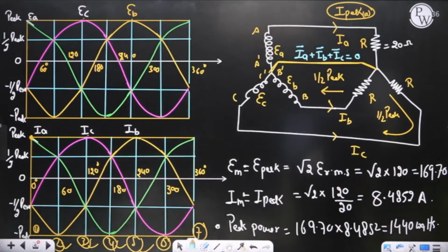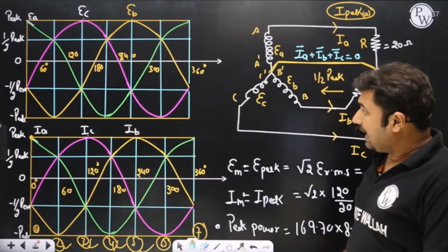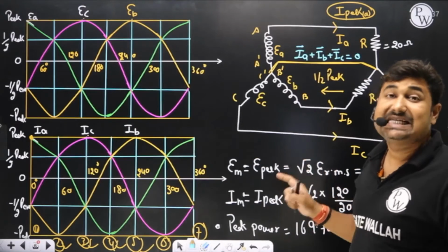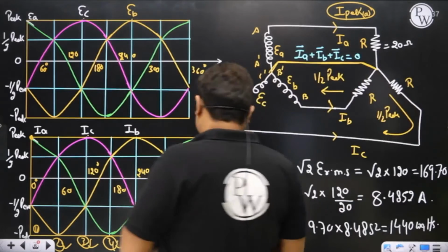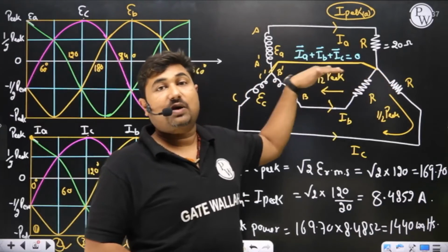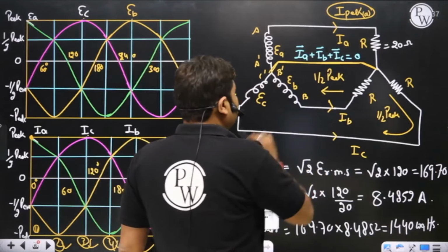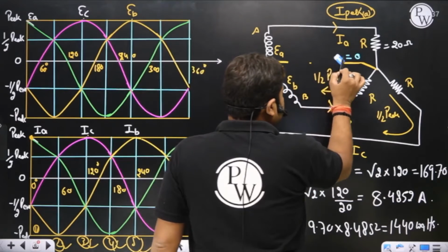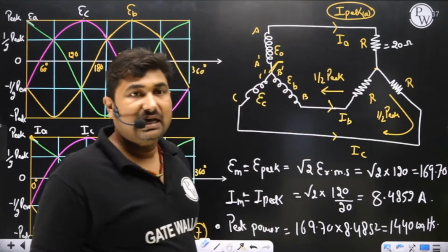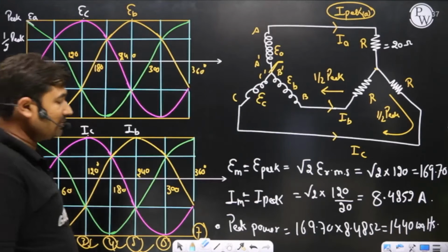Okay, now please see. So, sir, IA, IB and IC are equal in magnitude but displaced in time by 120 degree, and therefore you can say, sir, this neutral link is not required. In a three-phase system, you may eliminate this neutral link, sir. This neutral link is now not needed, because IA plus IB plus IC is clearly observed to be equal to 0 at any instant.